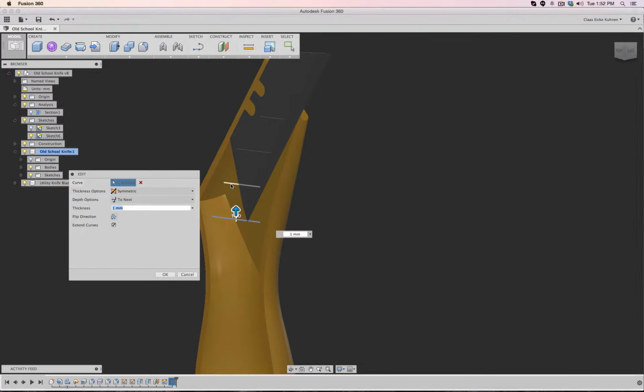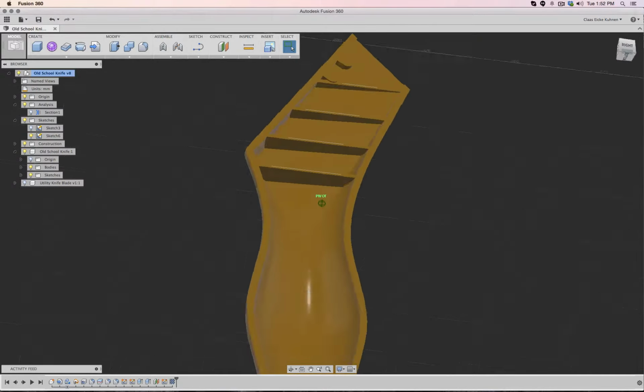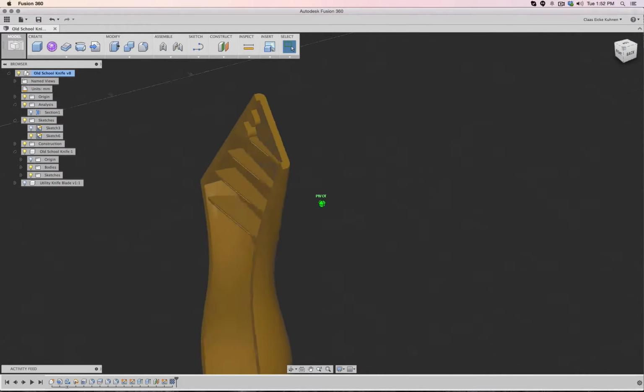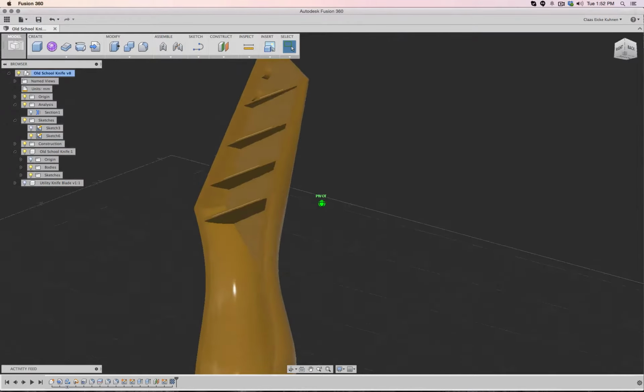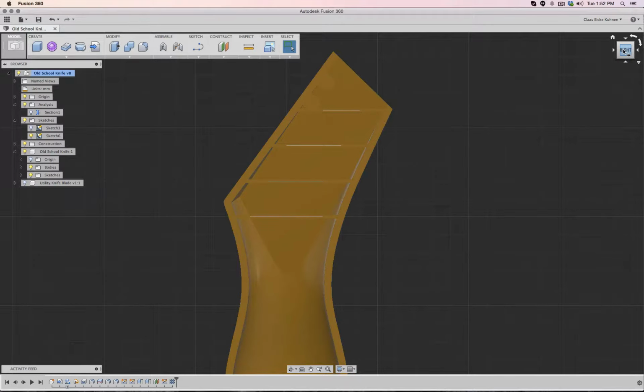So on the Mac side again, I click Command and hold it, so I can select all these different lines. Okay, let's hide the blade. There it is. Very easy and pretty fantastic. Now what I did here is complete, it works, but in terms of casting it is complete nonsense, because I create a small enclosed area that later is going to be a major pain. So I'm going to adjust everything a little bit.